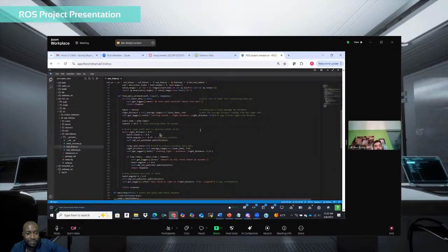And here's a pretty interesting thing. You'll notice right here it rotates until a wall is detected within approximately 0.3 meters. However, my right wall distance I have listed as 0.5 meters. This is the issue I've been talking about with the wall finding and the wall following. If I had used proper indexing from -180 to 180, I feel like this issue could have been mitigated or prevented altogether. So you had to make it big on this one to allow room for error. Yes, I did, because otherwise it wasn't working properly.